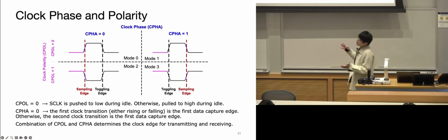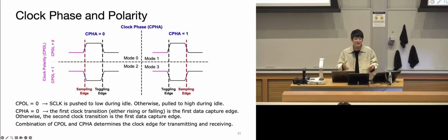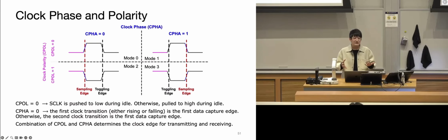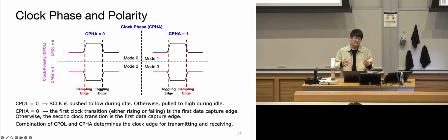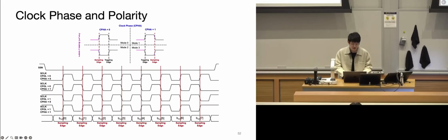It might look a bit confusing. This is usually due to historic reasons, because SPI is quite a flexible communication protocol. So every manufacturer can, actually they did, determine their own configuration details. Basically, the clock polarity means whether the clock is idle high or idle low. So maybe the next figure is a little bit clearer.